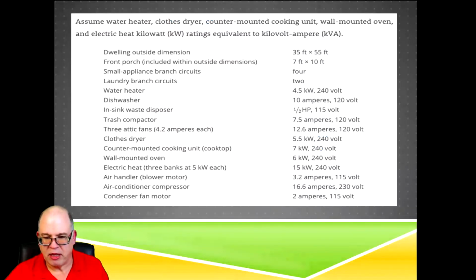So let's move back to our calculation, or back to what we've got going on in the presentation. Now, several things I told you up front. Even though this heat right here is going to be considered separate, and it is not more than 4, it is 3, we are going to add the blower in it because the way this one's designed, and I'm telling you this up front, and on your exam it'll tell you that as well, we're going to consider the air handler in because it also is going to be utilized to blow that heat.